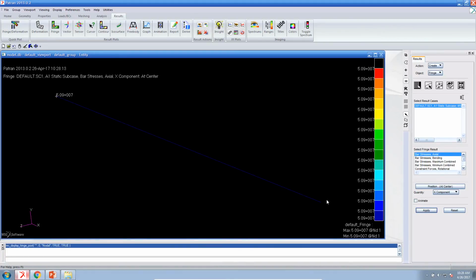It then will hit the limit of the constraint of 110 megapascals. Our initial design, as you see here, is currently at 51 megapascals. You're going to see the radius shrink, but the axial stress actually increase until it hits the upper limit of 110. So now let's go through the process.